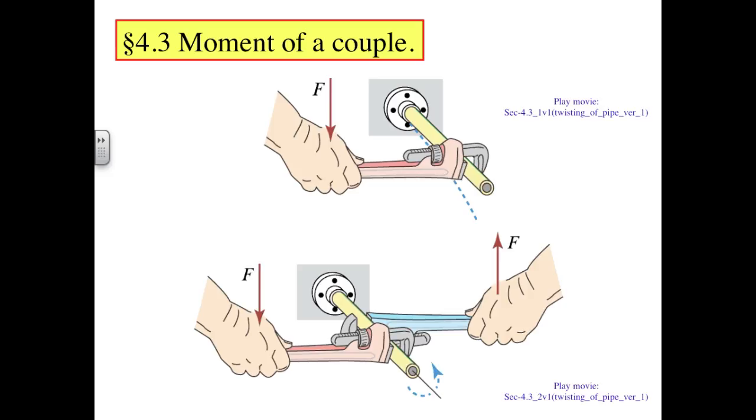The friction forces are tangent to the bottle cap and equal and opposite as you move your thumb and forefinger in opposite directions during the twist-off. These friction forces constitute a couple, equal and opposite forces whose lines of action in this case are separated by the diameter of the bottle cap.